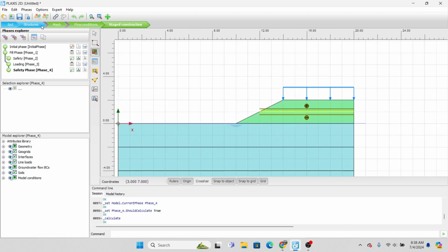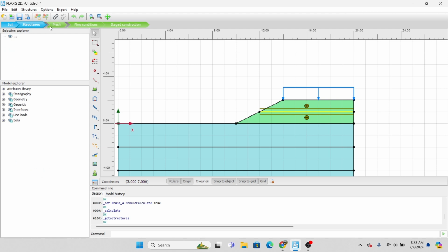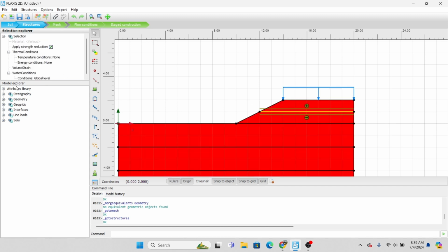But for example, you wanna increase the load, so you're gonna go back to the structure and press the select button, and you're gonna press the load, and you could change anything. So for this, I'm gonna increase it to 10 kilonewtons per meter, and for this, I'm gonna create a pseudostatic pressure, not pressure, load, and let's see what happens.